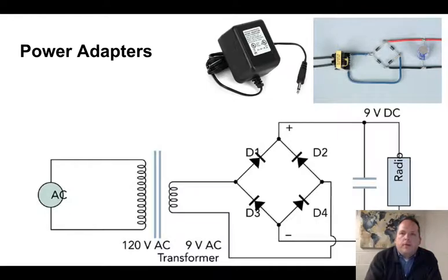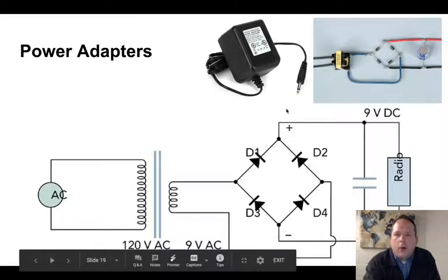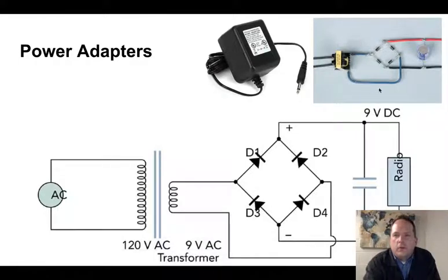All right, finally we've arrived at the physics of our power adapter here. So inside a power adapter, there's three devices, and this is actually a photo of the elements taken out of a power adapter. You have this little thing, which you might be able to see some coils of wire there. This is your transformer, changing one voltage into another. This is a network of 4 diodes, those little cylindrical shaped elements that we saw on the last slide. And finally, a capacitor over here, and then the 2 leads that go to whatever device I'm going to be powering with my power adapter.